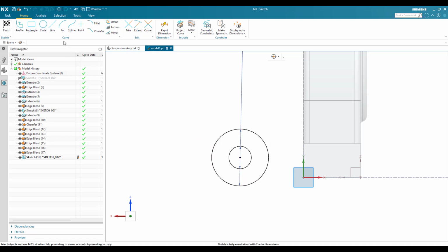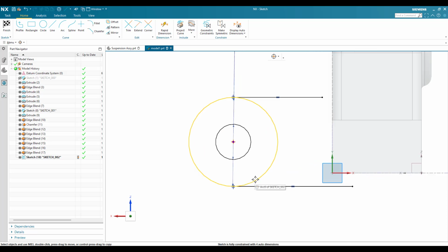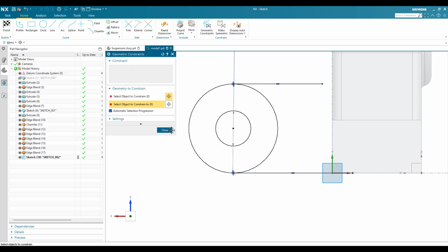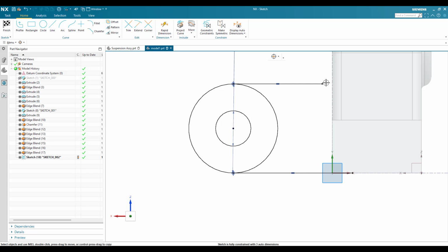Okay, so then there is a tangent line here. So this is the tangent line. This circle should be tangent to this x-axis, so press C and go to tangency. So this line should be tangent to this, and now we are going to extend these two lines